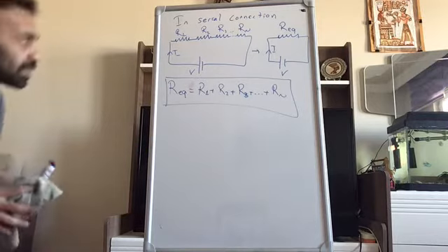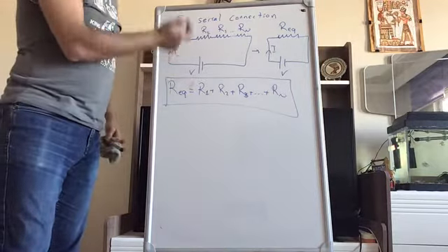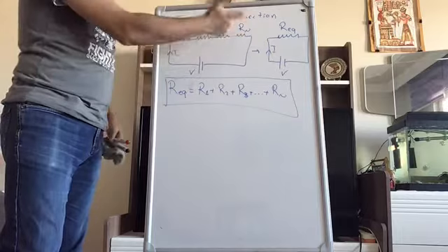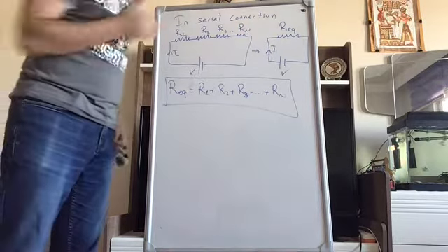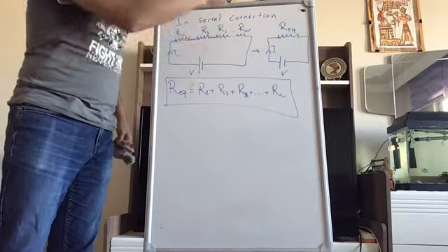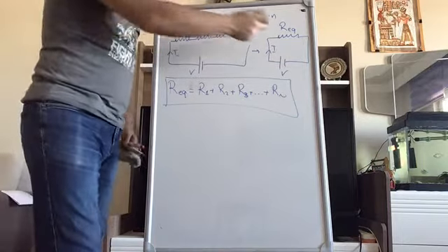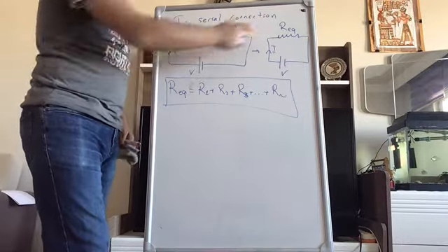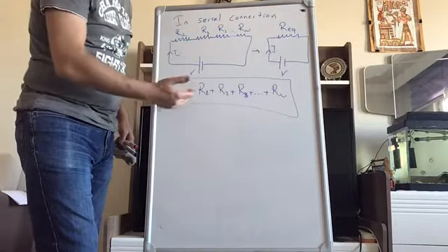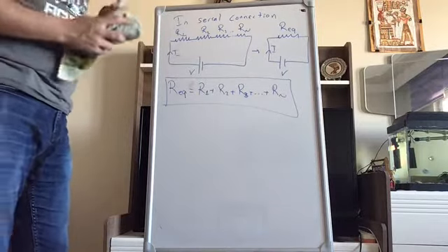Okay, so this is one way you can connect your resistors serially, let's say like your light, your heater, your phone, your robot and some other things. So you can connect them serially to each other, or if you want to have only a single one doing the same job, with the R equivalent, you can calculate R equivalent in the serial connection simply as a summation of the whole resistance in your original system.